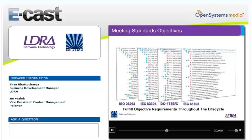So if you are familiar with DO-178 and you've read the standard for commercial avionics, you've gone to the back of the standard and you've probably seen a bunch of tables. Those tables are the ones that are finally used for the audit process through various control gates of the life cycle of the program. So in commercial avionics, you have Stage of Involvement audits, SOI 1 through 4, which check to see that you've written your development plan and your PSAC, the Plan for Software Aspects of Certification, and other planning documents properly up front.